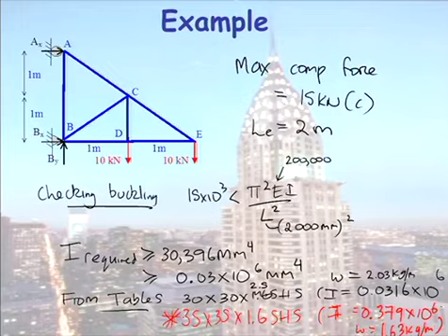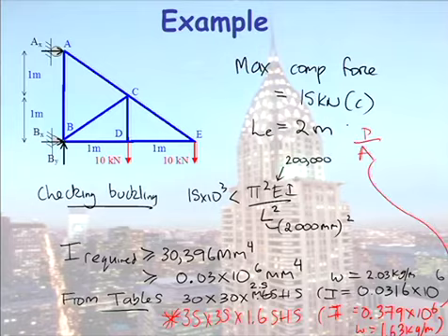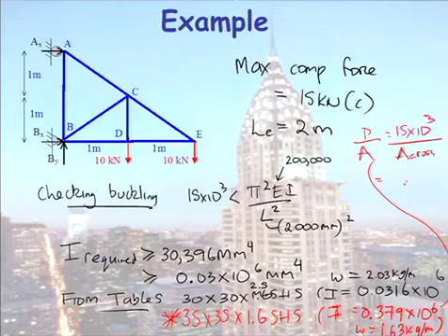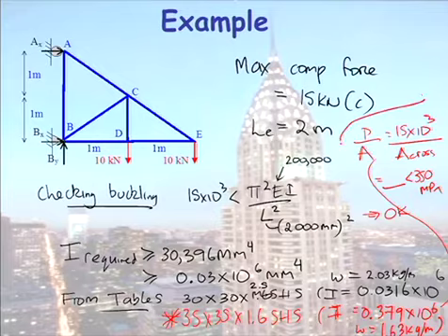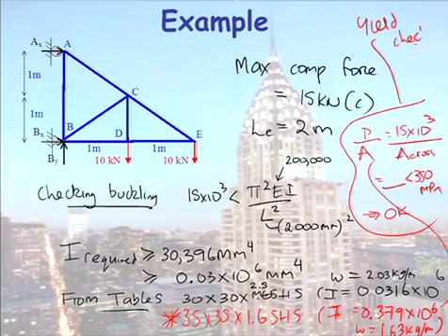Now at this point here, you would then say, okay, force on area. You would put in your force of 15 kilonewtons. You would divide it by the cross-sectional area, and you would get a stress value. And if that is less than 350 MPa, you would say, therefore, your section is okay. So that's your yield check. So this now is our yield check, and that is based on the area from your cross-section.